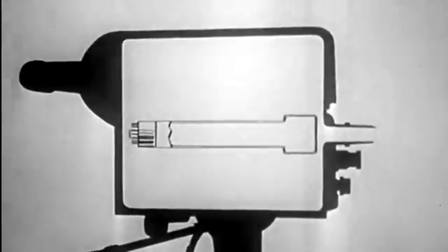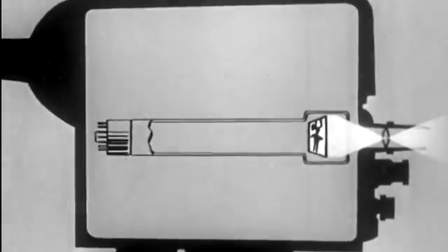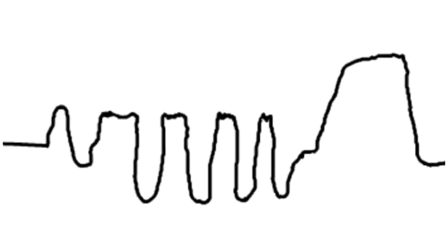To understand how that worked, let's start with the camera. Back in the 1940s, the television camera made pictures using a camera tube. The live scene was focused through a lens onto the face of a photosensitive plate at the front of the tube. That surface was scanned with a stream of electrons, which turned the original brightness and darkness of the scene into a constantly fluctuating voltage. The brighter the image at a particular point in the scene, the more voltage that would be produced by the camera tube. The electron beam was moved left to right and top to bottom to cover the entire surface of the photosensitive plate by two coils of wire around the camera tube.